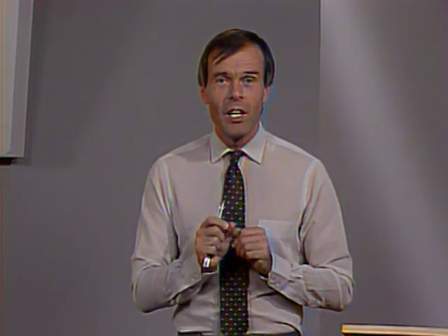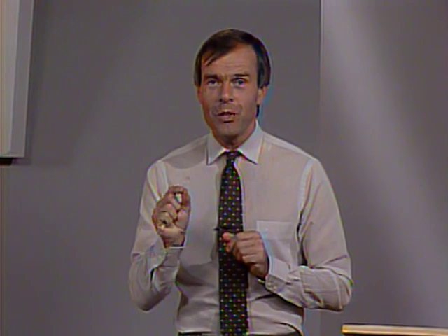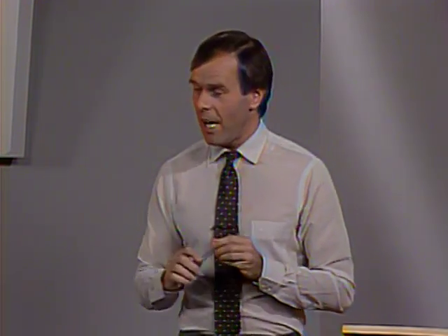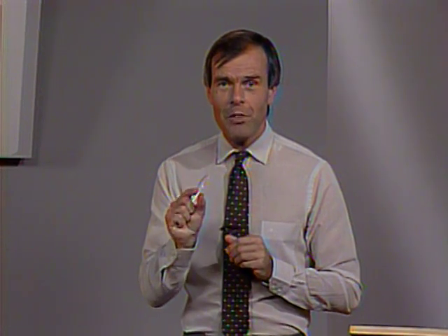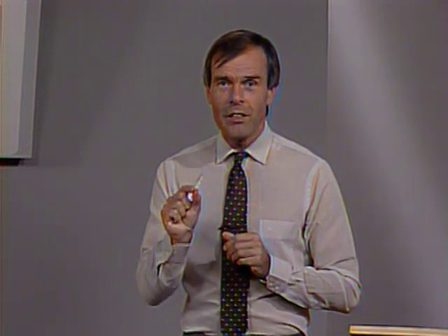However, in nonlinear analysis, as I mentioned in the earlier lectures, and you are now well aware of it, the frequencies change. The critical frequency, being the largest frequency in the system, changes. The smallest period of the system changes, as we are seeing here in this view graph also. And it is important that your time step is always smaller than the critical time step based on the highest frequency that you can ever encounter in the solution.